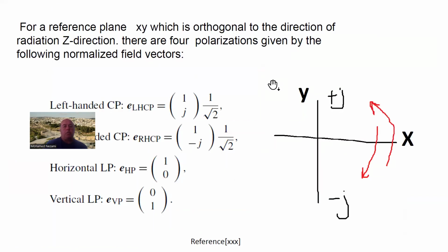So just to define the concept, what is circular polarization? It's basically an antenna which is fed in quadrature, or fed orthogonally, with 2 feeds of the same signal, and sometimes different signals, like in the case of Starlink, each the vertical and horizontal, even home SATCOM channels, where you have totally independent channels on the vertical and horizontal. So there are 2 separate information paths, but nevertheless, they still feed the antenna the same way.